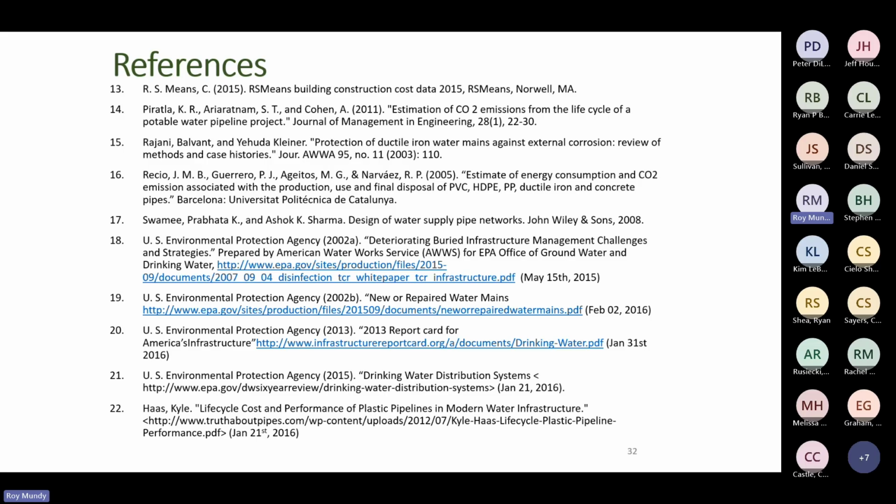Basically, not only does the Ductile Iron Pipe Research Association conduct tests all across the country on cement lined ductile iron pipe that is 20, 30, 40 years old, and basically come up with the same C factor today as when the pipe was installed, which is usually even a little higher, by the way, than 140.